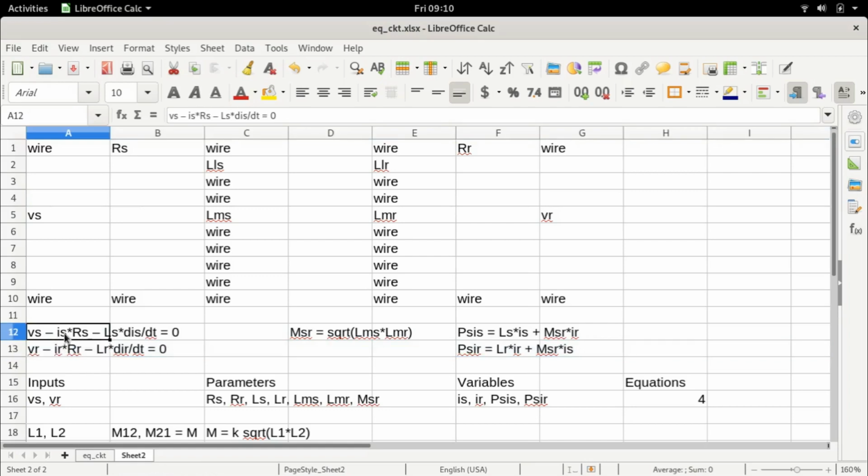It's very important that whenever you build any mathematical model, you always stop, analyze the equations, and go back and make changes as and when needed. One very important criterion is this: when you see a KVL loop being applied between two systems that are actually interlinked, but you don't see an interlink in the equations themselves, you know something's wrong.